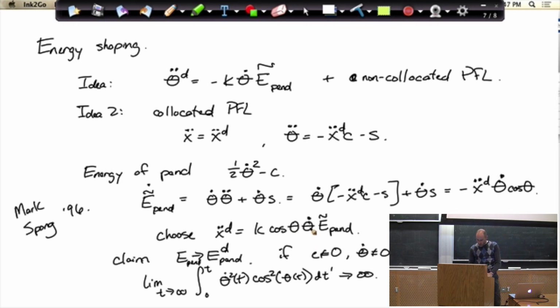But with that sort of moment of brilliance, you get these controllers that you can prove. Now the actual controller you'd want to run on the pendulum, this thing stabilizes the pendulum, but not the cart. So we've promised that this thing's going to go up, but it could be that our pendulum just goes off, or our cart goes off to the side and just walks away.